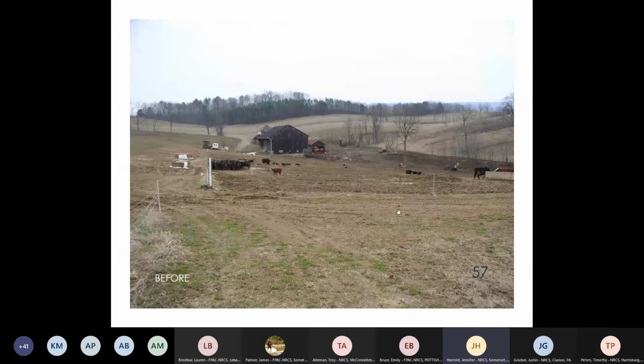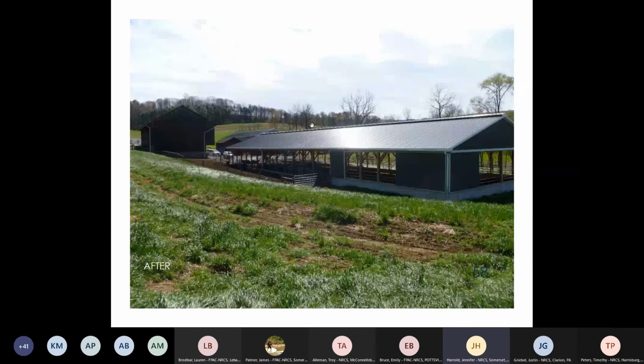and use those nutrients whenever you're going to be planting crops or putting on hay to get it to grow a little better. Another beef operation where you have several acres disturbed, manure-laden runoff at its finest, and close proximity to the stream. We came in, did a large roofed heavy use area and stacking area, and a diversion was built above to divert the 25-year storm, and eliminated any brown area. And that's quite an improvement from several acres to this small, confining them to this small area.